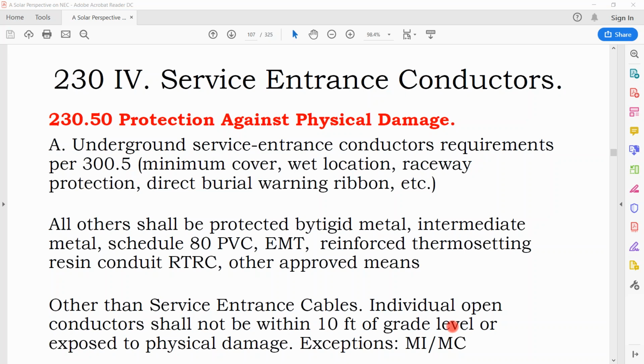You can buy the metal wrapping separately and pull the cable through the metal wrapping. It's hard to do. So they call that something else. They'd call that flexible metal conduit with cable inside, whereas the MC, the metal clad cable, comes pre-bundled. That extra metal jacket gives it a little bit more physical protection.